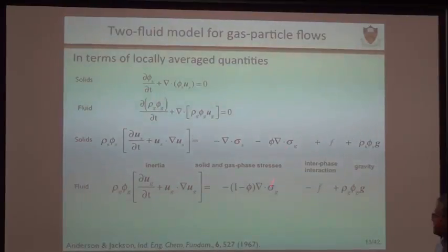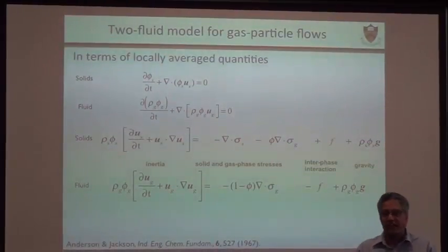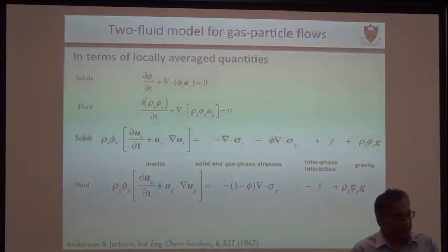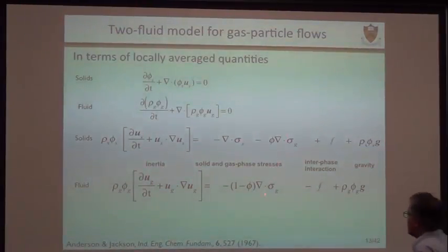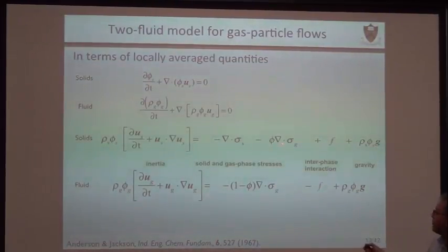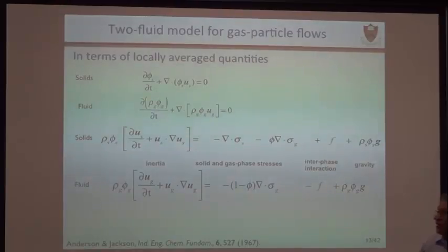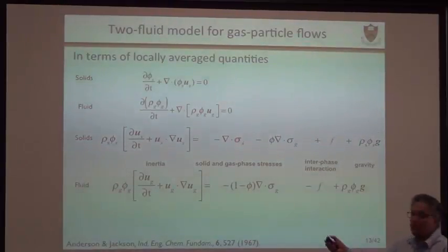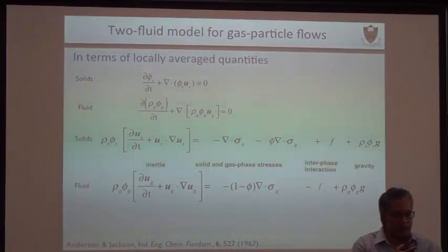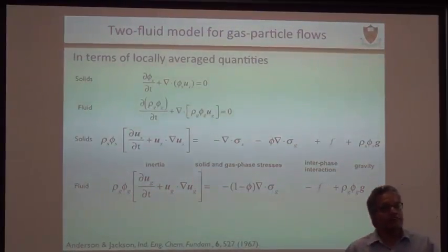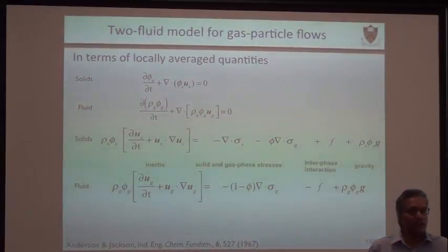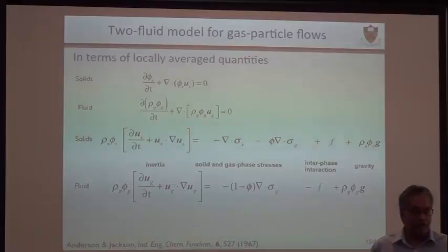Then for the gas phase, you have the pressure in the gas phase, and you can talk about viscous stress, so there is an effective stress in the gas phase. And then there is what we call the effective buoyancy force generated in this problem, which goes into the gas phase. And the particle stress comes in because, as you saw, the particles are colliding with each other and transferring stresses with each other. So you have various mechanisms by which particles transport momentum. That's basically the framework for all of the models.